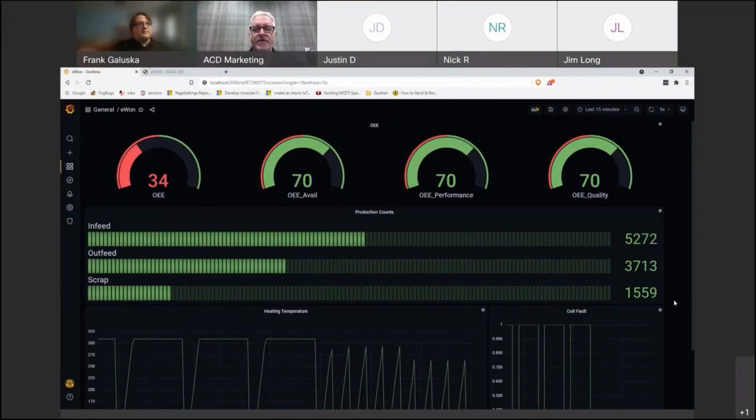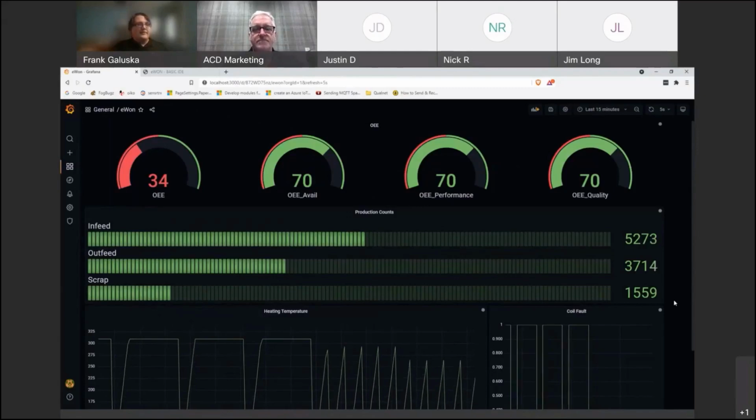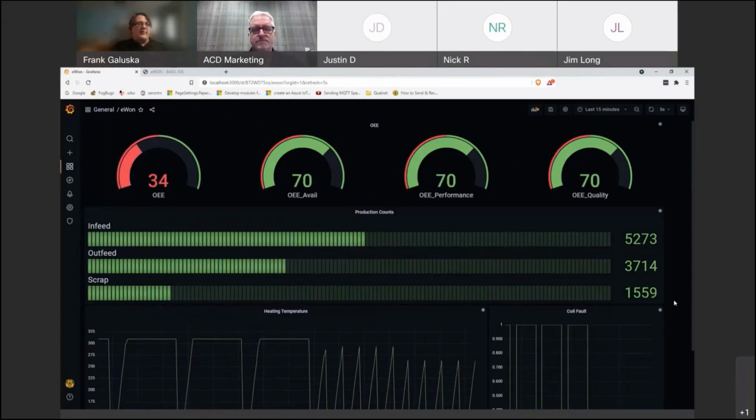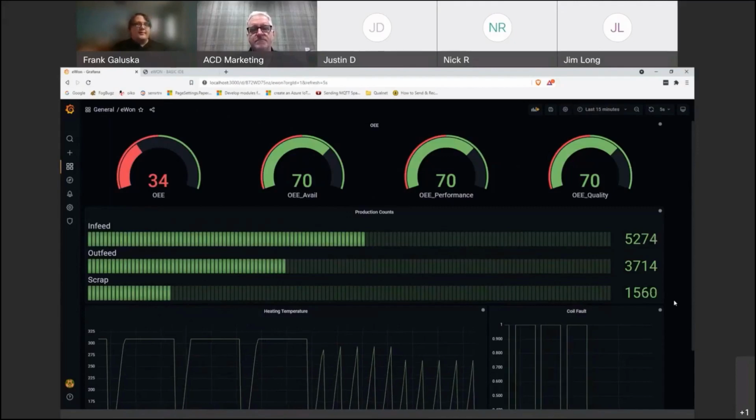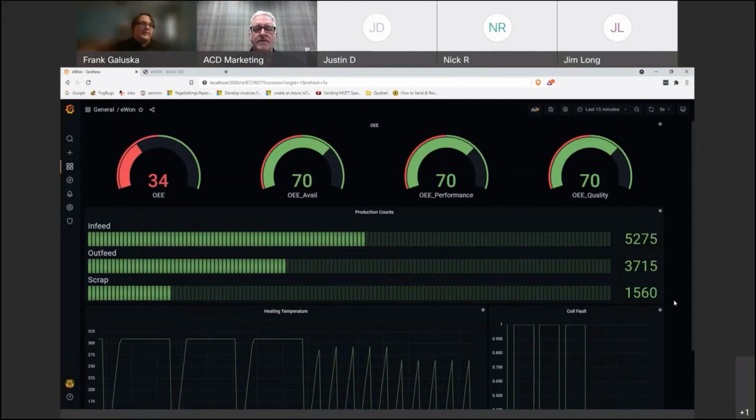what I'm seeing from this, Frank, is this is far, far from rocket science. That makes sense? Yeah, once all the pieces are there, it's just establishing your data flow in the right way, and making sure you have the Ewon getting data from the Siemens PLC and pushing it out to a data broker, so that it's available to platforms like Canary and Grafana and anything else that can subscribe to an MQTT data broker.